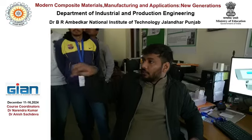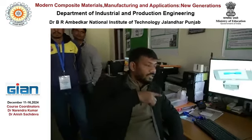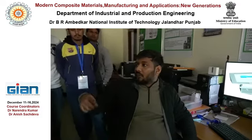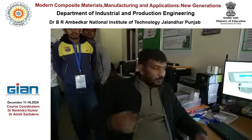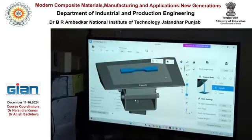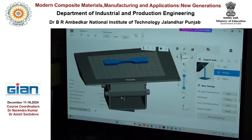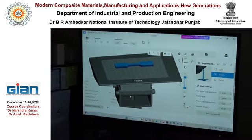It is very difficult to remove the resin from the platform, so you need support, but the support also takes much time. So here we won't take the support, only to reduce the time, but in actual part printing we have to take the support.